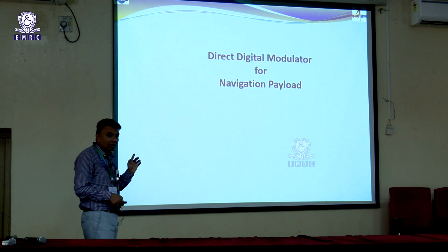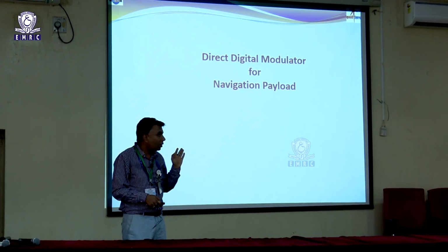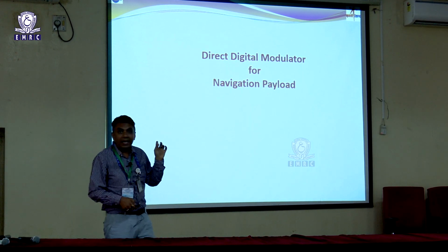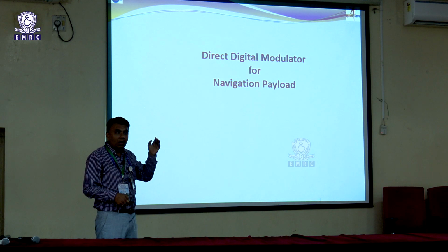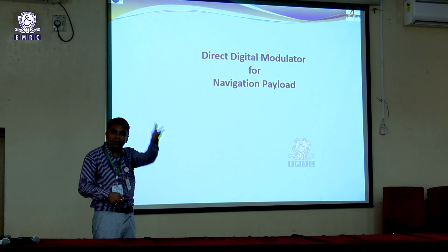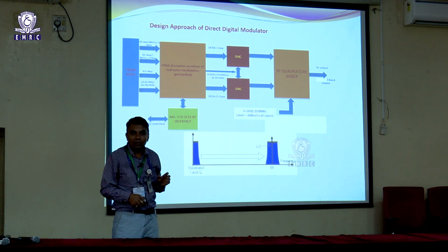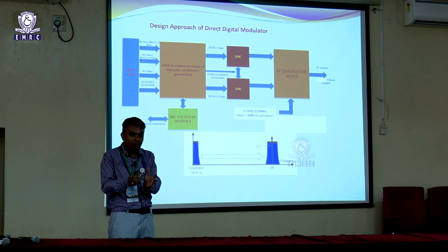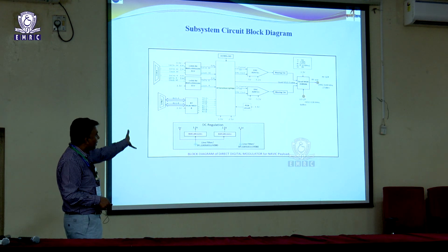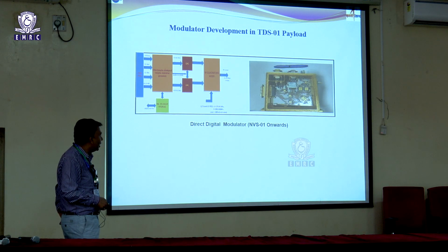Digital modulators: this is very important, this technology we have now transferred even to Indian industry. This is a good part. Now you know that in NavIC we have 3 bands, L1, L5 and S band. So, this is like an SDR design where it is independent of frequency. You can configure it on board for either L1, L5 or S. This is a common design, and any modulation you can configure from the ground itself. The concept is basically a zero IF based design. All the modulation happens in zero IF, and based on your command it can be configured in the L5 band, L1 band and S band. It's a common design approach. This is the internal flow of the modulator. This is a snapshot of the FM model which has been flown in the NavIC satellite.